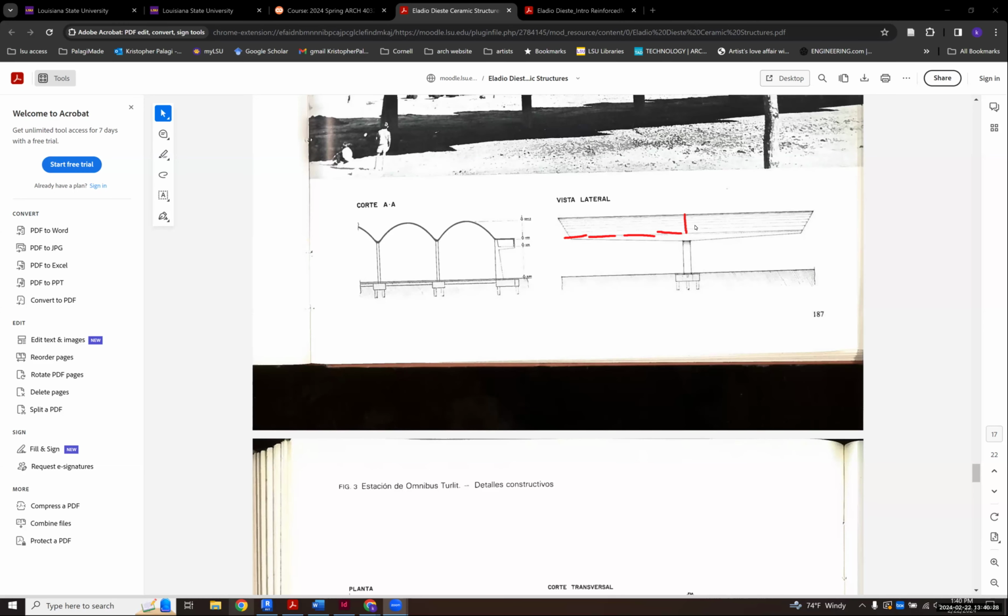So I'm gonna rebuild this, I'm gonna build this for the first time and not screw it up like the time that I didn't record it. This is the first time. So just looking at this vault, I want to show that I'm going to use just a basic ratio of about the depth of this vault being about 25% of the cantilever.